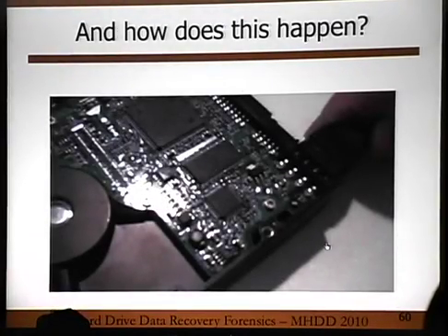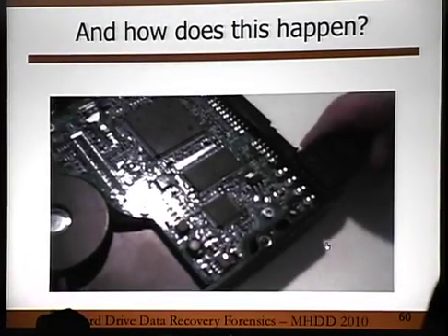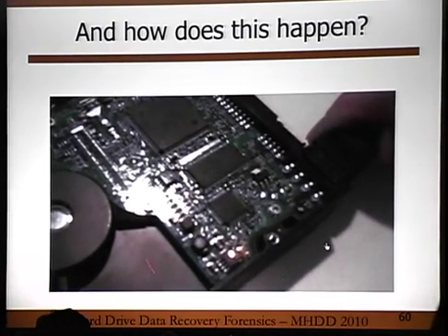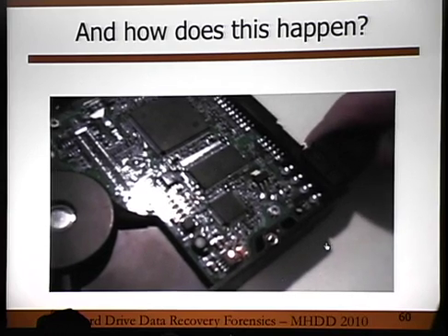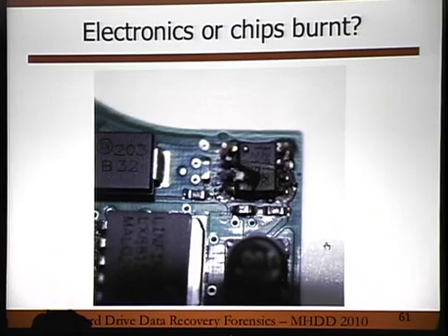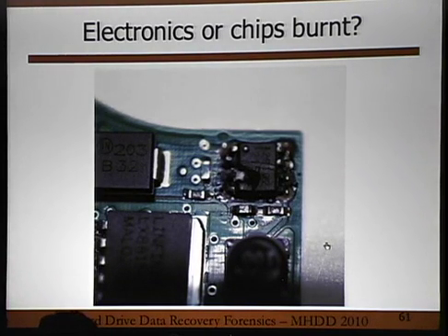So on your electronic stuff, how do they basically burn? I'm going to go a little faster here for a second. This is what happens when you plug one in backwards. See down here in the corner? Smoke, fire, blah, blah, blah. That happens all the time on Mac store drives. It's a very convenient thing that the chip will burn. And this is the motor control chip. This chip basically will cause the motor to spin, and without that chip, it won't work. So you could just swap this board, but if you needed to, you can unsolder this. Sometimes it's not that obvious. Most of the time, you can tell by...